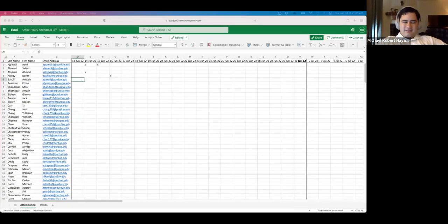So last time we went over the syllabus and then we started our discussion about the operational amplifier. But since we want to be on good speaking terms with the op amp, we are going to call it the op amp. The idea is that it takes in one or more input voltages and produces a linearly related output voltage. Linear as in linear differential equation. So we'll see today that it can do derivatives and integrals and things of that nature. And it can do all these sorts of different mathematical operations, and mathematical operations is the reason for the name operational amplifier. That's why it was constructed. It was to be part of analog computers.